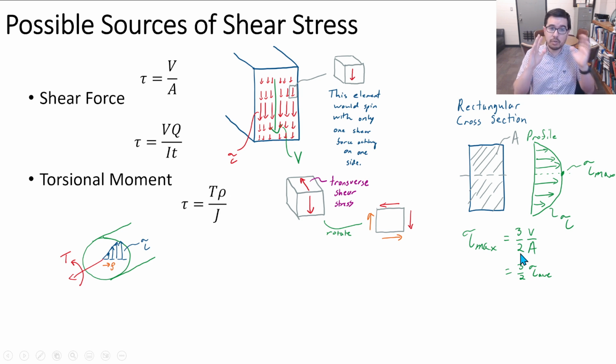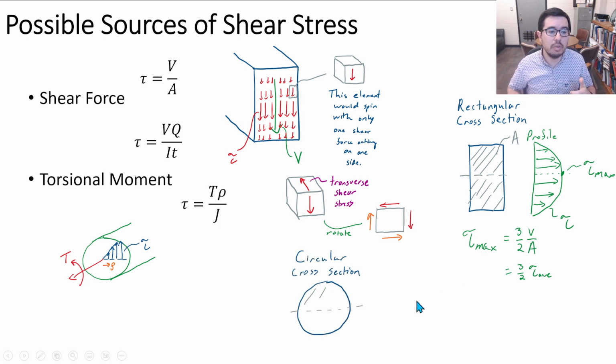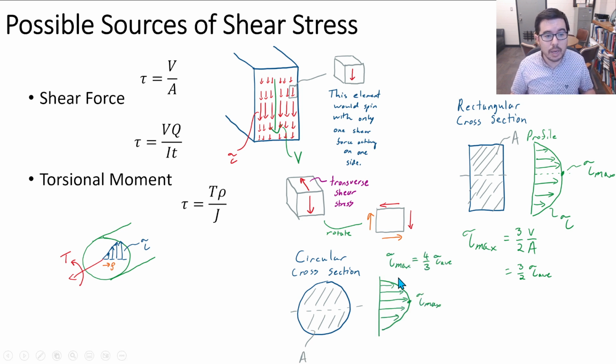This is a very valid formula for calculating a transverse shear stress on a rectangular cross section, but often we'd combine loading. Since there's the twisting of the beam or the shaft itself, we are looking at circular cross sections. And so this formula is the one that can save you a lot of time. If we have a cross section and there's a transverse shear stress being applied to this face, and we're on the neutral axis, the maximum is going to be 4/3 tau average.